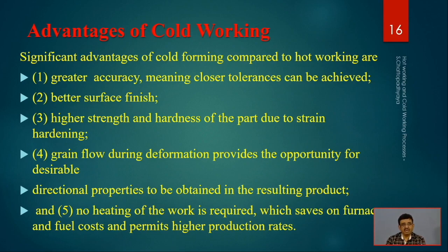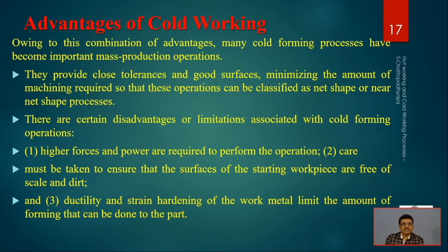And last, I have already discussed in the first, that heat is always a challenging option. So no heating of the work is required, which saves furnace fuel costs, permits higher production rates, and the tools and tackles do not have to be made of heat resistant type of material. So that is always a terrific advantage. Owing to this combination of advantages, many cold forming processes have become important for mass production operations.